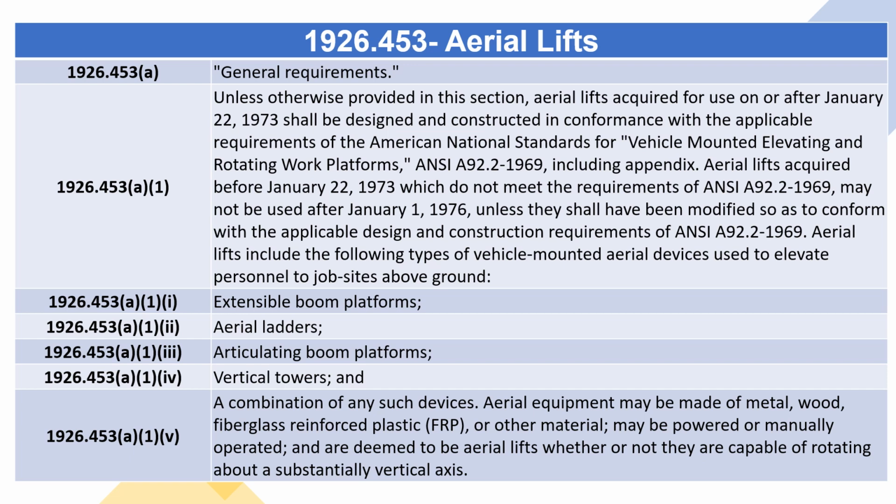Aerial lifts acquired before January 22, 1973 which do not meet the requirements of ANSI A92.2-1969 may not be used after January 1, 1976, unless they shall have been modified so as to conform with the applicable design and construction requirements of ANSI A92.2-1969. Aerial lifts include the following types of vehicle-mounted aerial devices used to elevate personnel to job sites above ground.